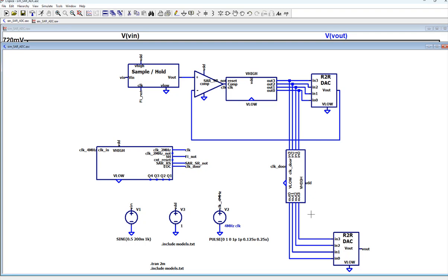We spent a week on the D flip-flop, remember? We verified all the signals on every single line. We verified that it's rising edge triggered, because when the rising edge arrives, D will be copied to Q. That's the first thing we verified. The second thing is that after the rising edge, if D changes, Q does not change.